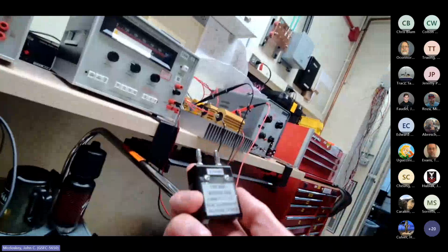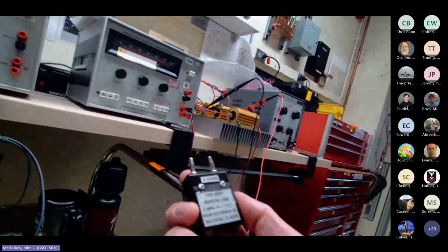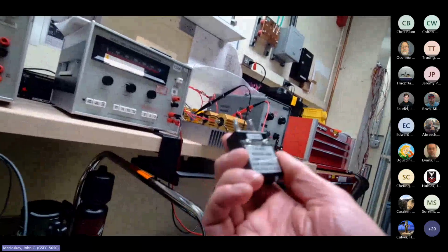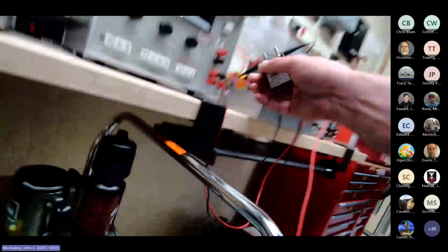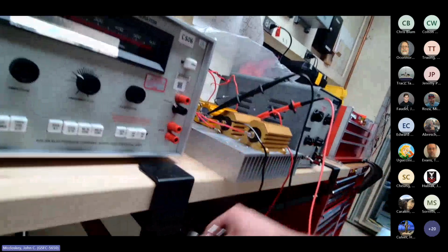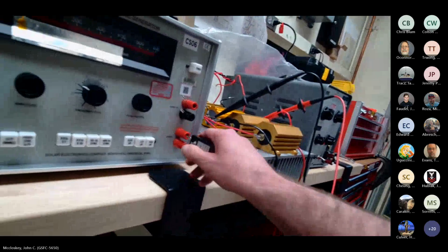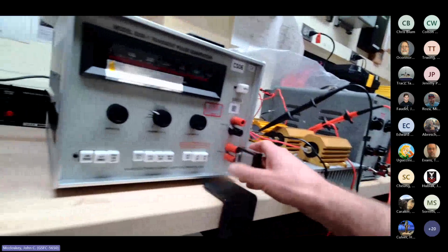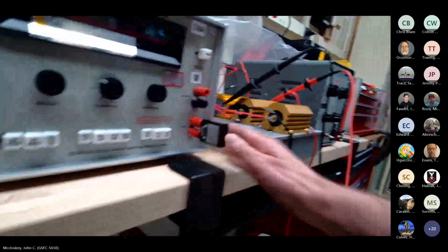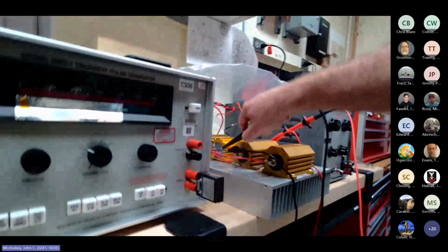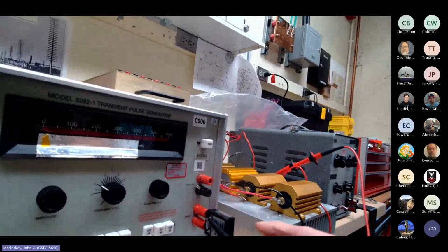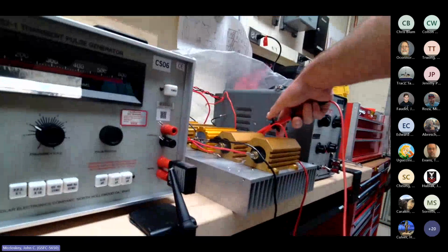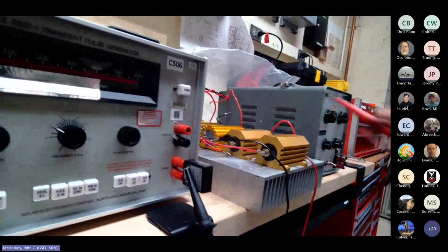But when we were testing this setup out, Rob found these. It's like, well, that's what we should be using. So let's get rid of this crappy transmission line and just plug this directly in. And then we'll move our connections. And remember, for the 150 nanosecond pulse, the polarity is reversed. So positive is going to be on the bottom.